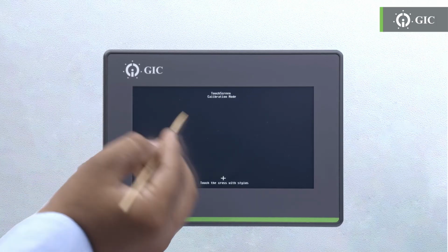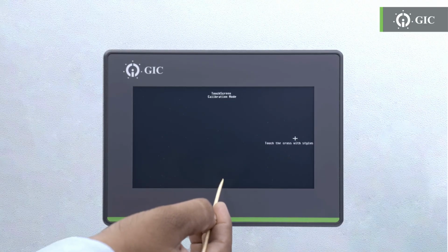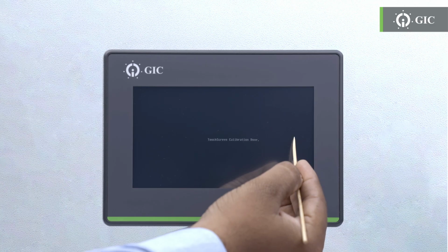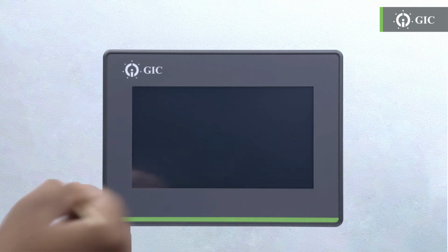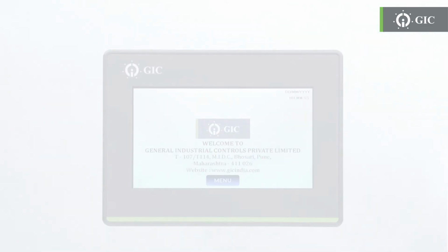Step 3. Now, press on the plus sign at the bottom of the HMI screen. Step 4. Finally, press on the plus sign at the middle right, the third calibration point. Release it, and you're done. As the words "touch screen calibration done" appear on the screen, your HMI will boot up and is now ready to respond.